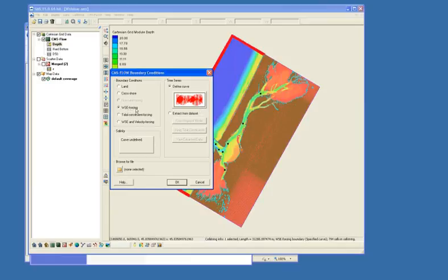so for the water surface elevation forcing, you would want to extract from a data set using tidal constituents. And there's an option here. I'm not going to show this right now, but basically you'd be able to link up with one of the databases, choose how frequently you want to build a water elevation signal based on those tidal constituents, and then you would end up with a value at every cell along your grid of a representative water level curve for that.